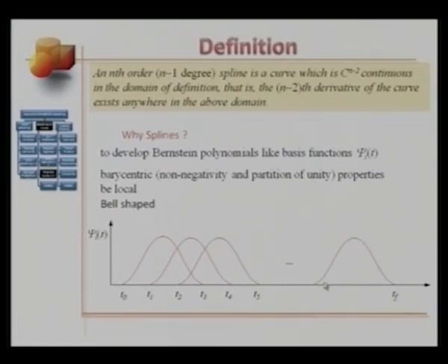Let's consider one of these functions and try to design that function. Let's say, number 1, that this function is a cubic polynomial. Number 2, that it is designed in a similar way as a piecewise continuous curve that we had seen when discussing Ferguson composite curves and Bezier composite curves. Let me explain this on the board.